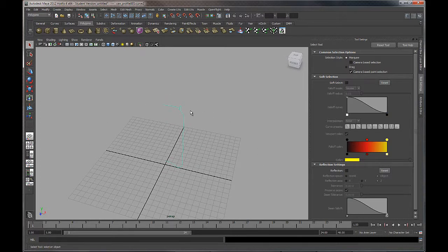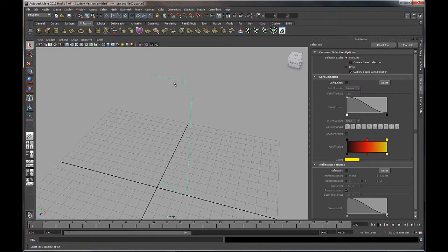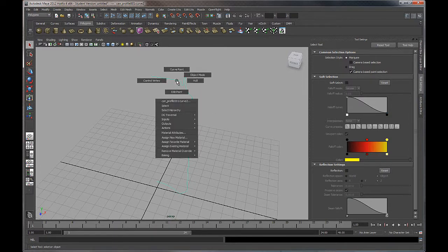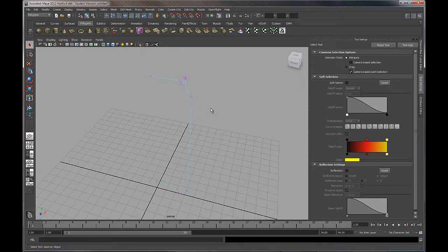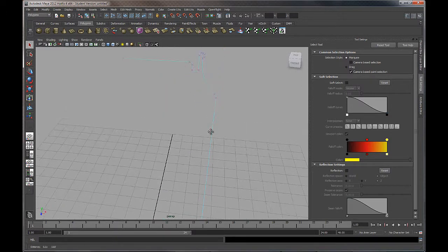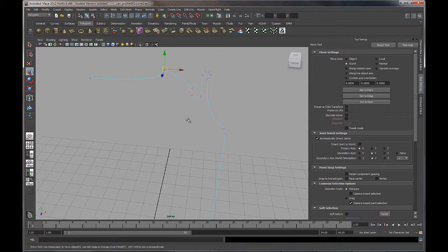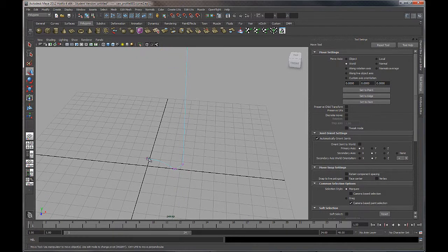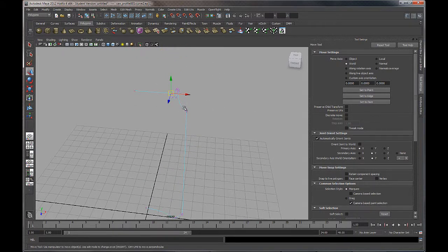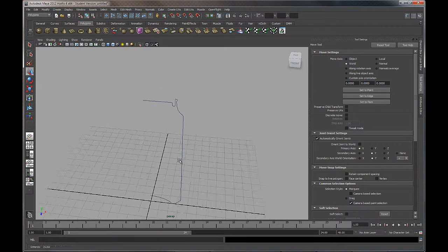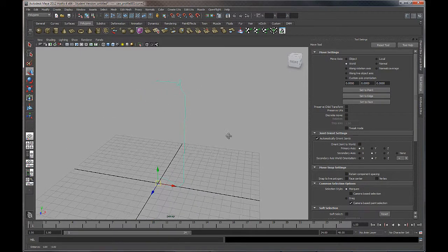Okay, so this is just a curve. To have a quick look at the curve structure, if I right click here and I select, let's select edit points, you get these little purple crosses everywhere. Now these are the anchor points that I created in Illustrator. So these are all the positions I clicked in Illustrator. Now technically I can move these around inside Maya. I can use the move tool and start messing around, but it wrecks the shape of the object, and obviously we don't want to do that. But you can see there that you can actually edit the shape of the curve in here once you've imported it. All right. We're not going to do that though because it'll mess the shape of our can up completely.